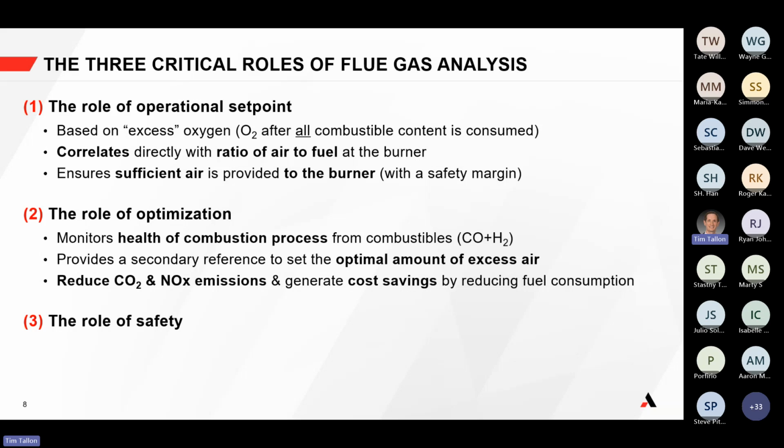As you lower to a more optimal excess air set point, you also reduce your CO2 and NOx emissions and generate a cost savings by reducing your fuel consumption. So there's a direct return on investment, both on the environmental side as well as on the financial consumable fuel gas side of things.